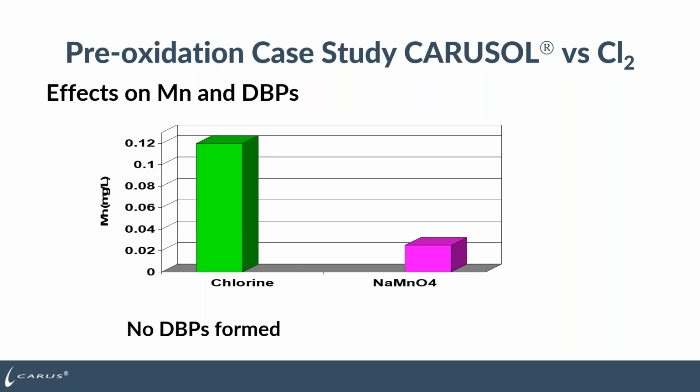But then in the clear well, as the water sat with additional chlorine, it would start to turn yellow and they would get more manganese drop out, and the last bit of the manganese would come out in the clear well, which was bad because obviously you're dirtying up your clear well, you're going to send that out the door.